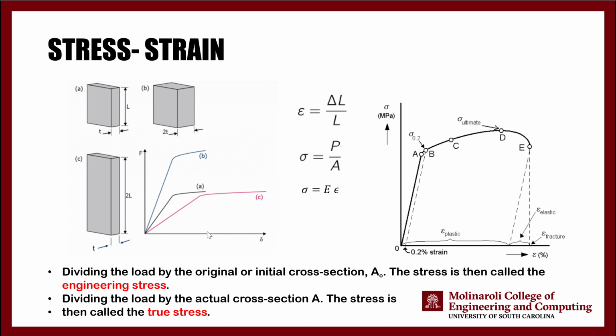Okay, so based on this Hooke's law, we can see that we can define a stress and a strain instead of load and elongation. Essentially, when you divide your elongation by the original length, the initial length of the material, or any base length, it doesn't have to be the initial length, but we usually use the initial length for analysis, we can calculate the strain of the material. And we can define a stress as our load P divided by the cross-sectional area of the material.